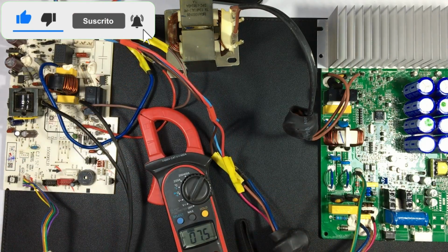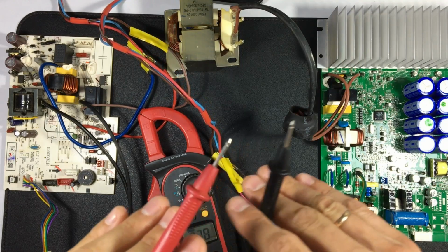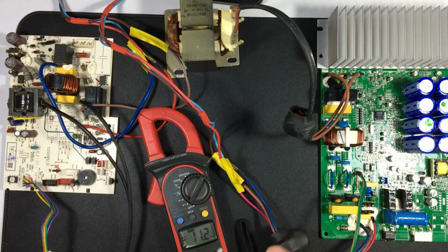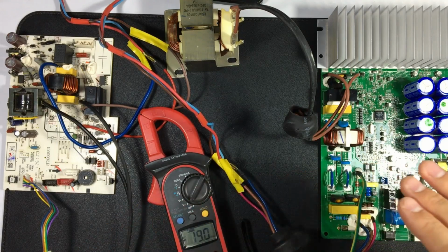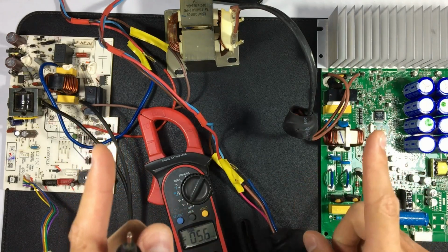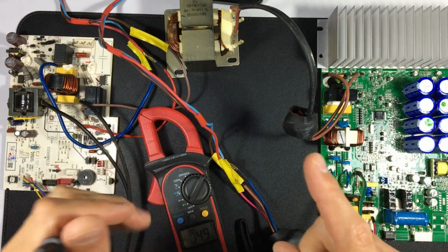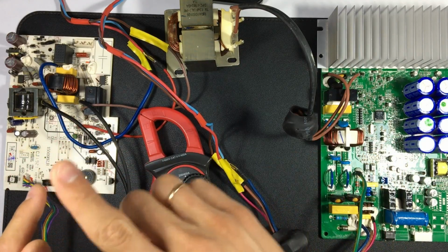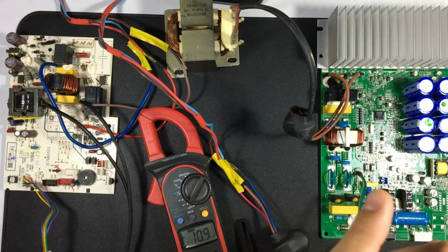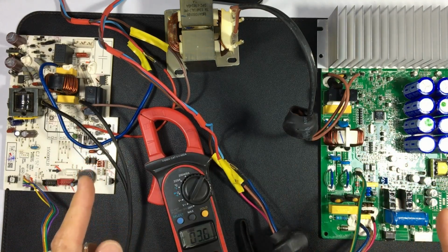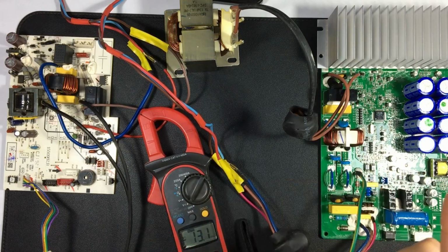That data is important. That variation is important. Do you notice that there is an intermediate voltage? It is 15, it goes down and goes up. It goes to 2, it goes to 22, to 2 and to 22, and goes back to 15. That's how an indoor unit communicates with an outdoor unit. When the voltage drops, one communicates with the other, and when the voltage rises, the other communicates with the first. That's the way they have to communicate with each other.